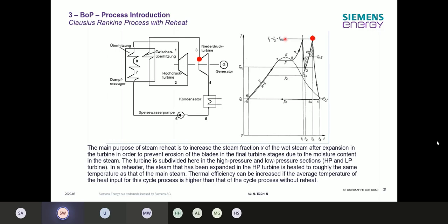In some power plants, I already saw that the temperature is even higher than on the HP part, because that's depending on the steam turbine. On the HP part, you have the high pressure and the high temperature. So the stress for the material is one time the stress coming from the high pressure, and one time the stress coming from the high temperature. These two together define our stress over here.